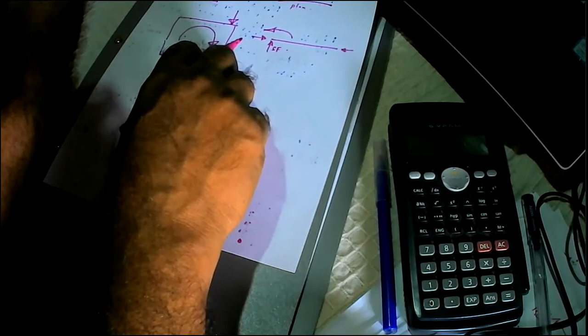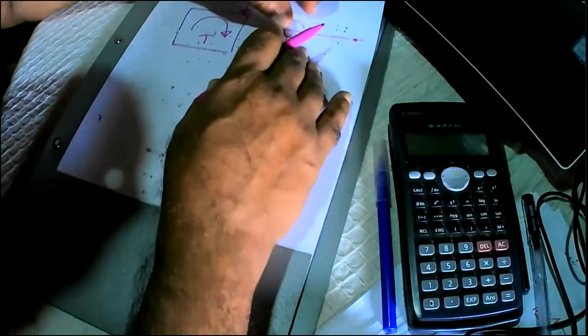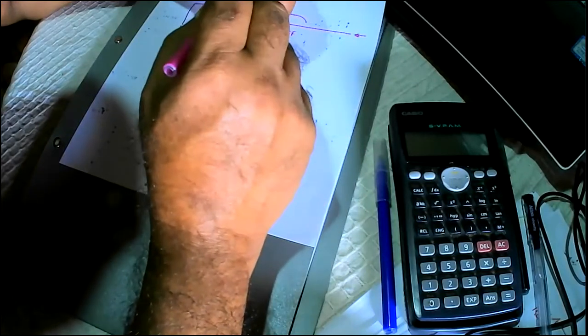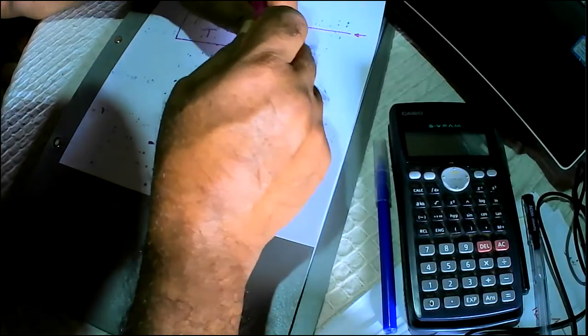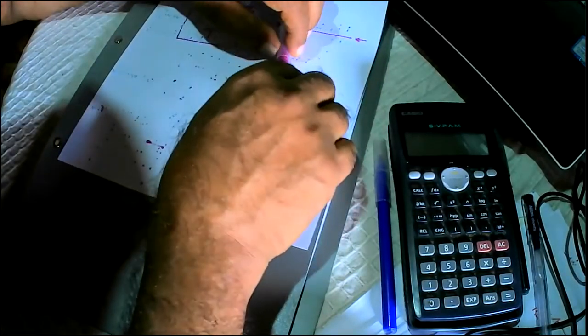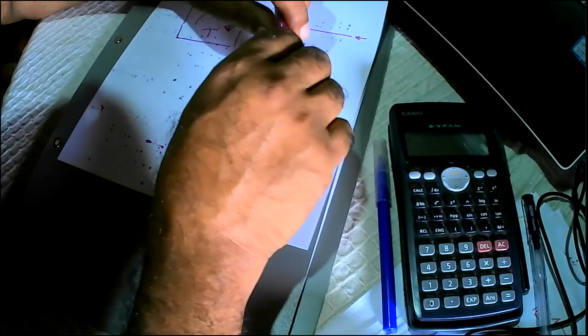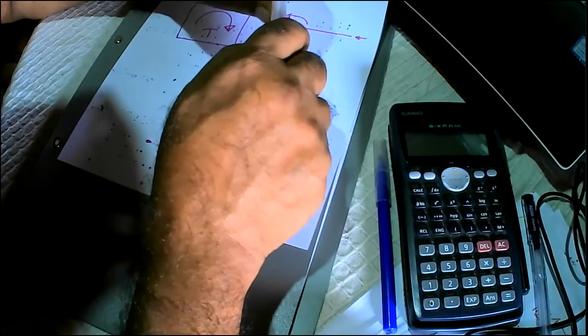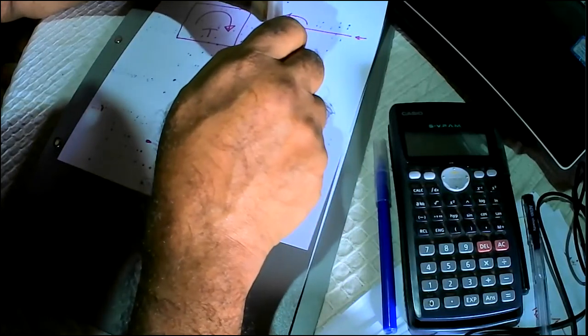And similarly, for many other elements, for example for slabs, we don't consider the deformation of the slab in its own plane, but we consider the deformation of the slab out of plane. So what is important for us is out of plane deformation of the slab due to the vertical loads, and we generally ignore the in plane deformation of the slab.